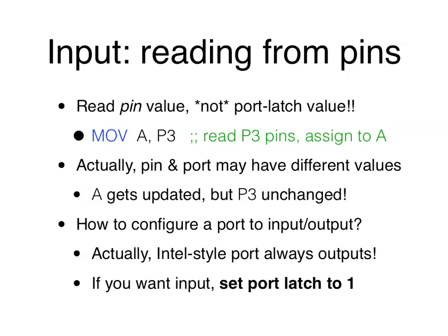This means if you want to input, you set your port register or port latch to 1. That makes it a pull-up state. In pull-up state, just like the button, somebody can leave it in pull-up or high value, or they could pull it down. In other words, while the port is outputting a 1, it's overridable. Somebody is allowed to pull it down or leave it high. But when it's in low state, there's no way somebody can pull it up. So that's why it's important.